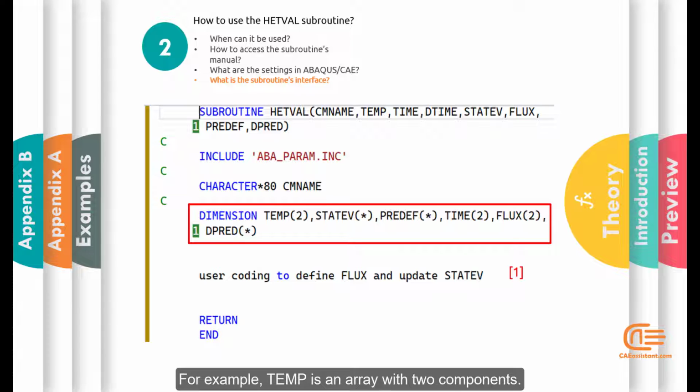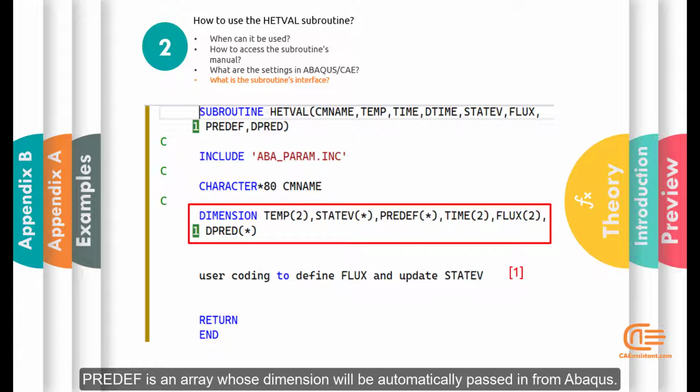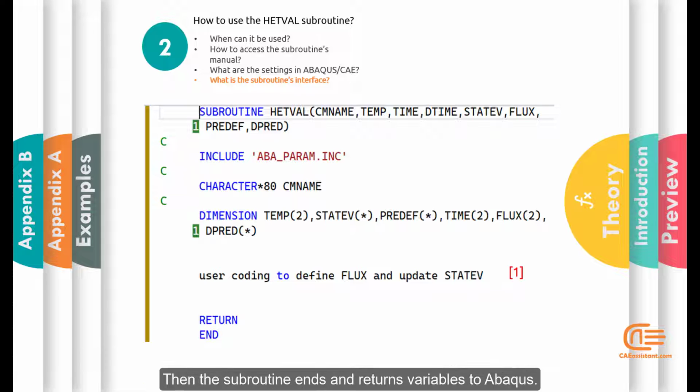For example, TEMP is an array with 2 components. STATEV represents the user-defined state variables, and its size will automatically be called from Abaqus. PREDEF is an array whose dimension will be automatically passed in from Abaqus. TIME and FLUX are arrays, each with two components. DPRED is an array getting its dimension from Abaqus automatically, so still we don't need to change anything in the subroutine until this point. The main contribution of our work is writing the user code to define flux and user-defined state variables in the subroutine. Then the subroutine ends and returns variables to Abaqus.